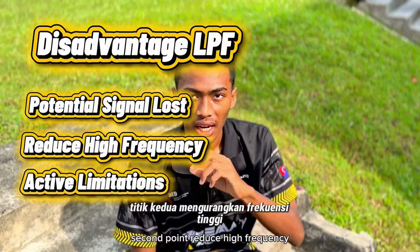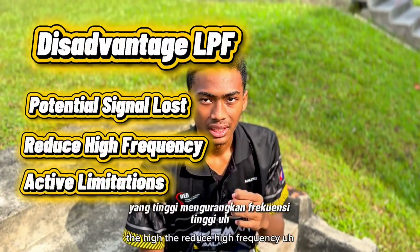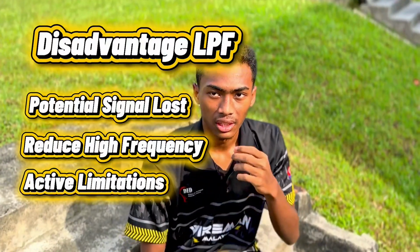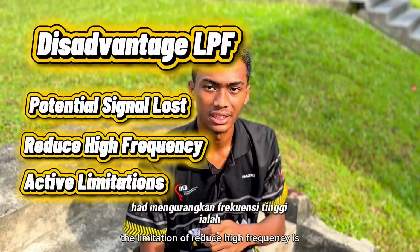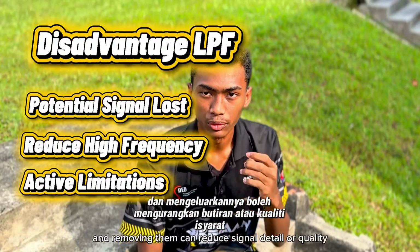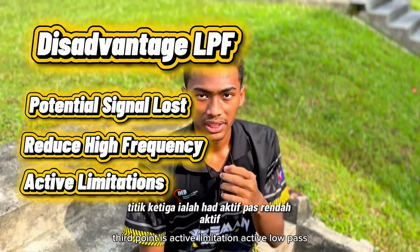Second point, reduced high frequency. The low pass filter reduces or removes high frequency components above the cut-off frequency. The limitation is that high frequency may sometimes contain useful information and removing it can reduce signal detail or quality.